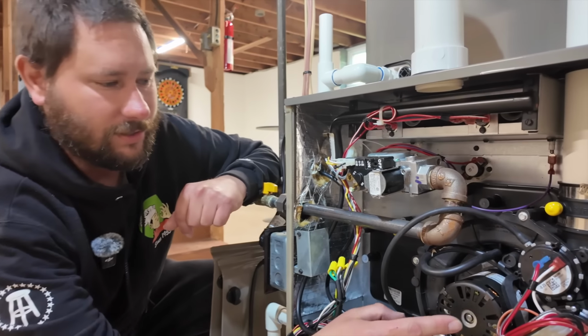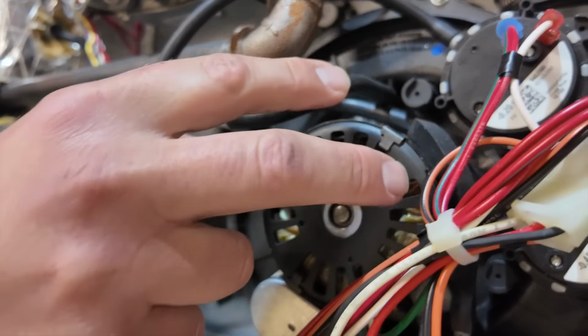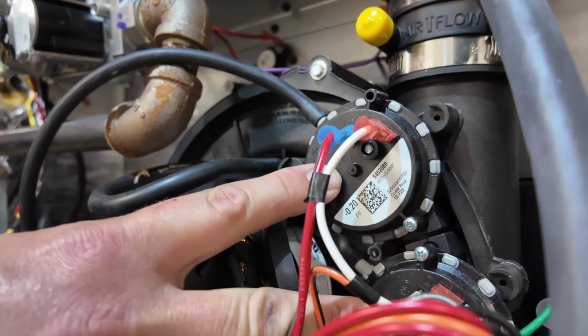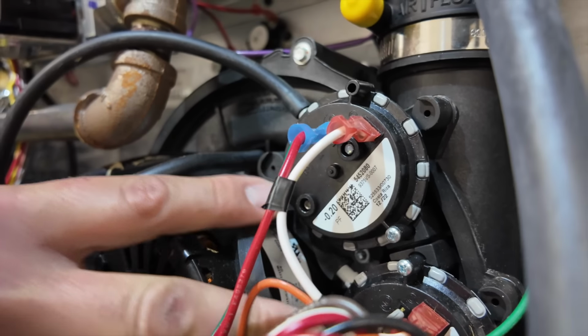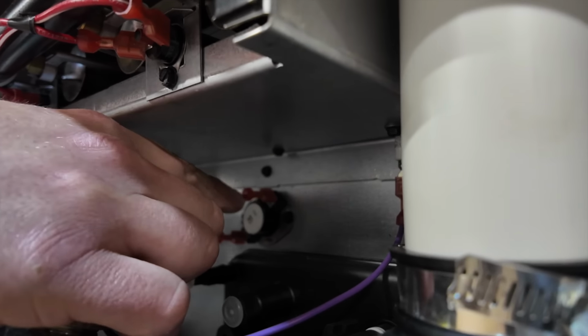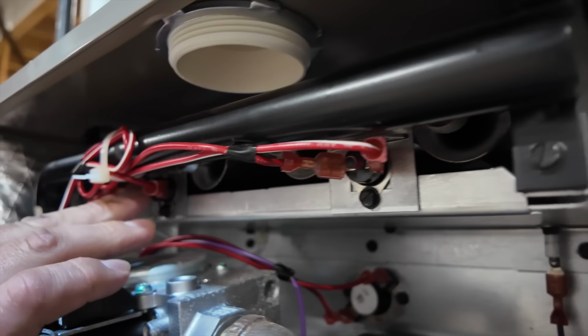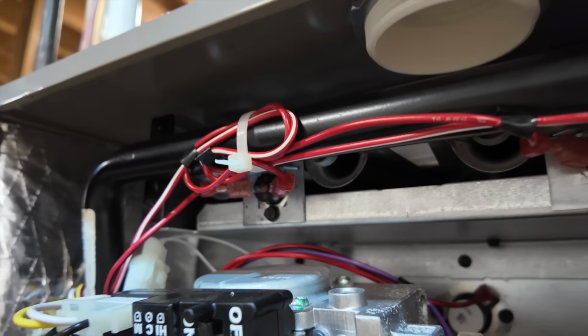Now that we've looked at the wiring diagram, the ladder diagram, and the schematics, let's dive into the gas furnace and identify all the components. Let's start with what starts first, our inducer motor. After our inducer motor, our 2 pressure switches should close. Then we've got our additional safeties, and there's one back here, and that's our limit switch. We've got 2 safeties up here. This is rollout number 1 or rollout number 2.